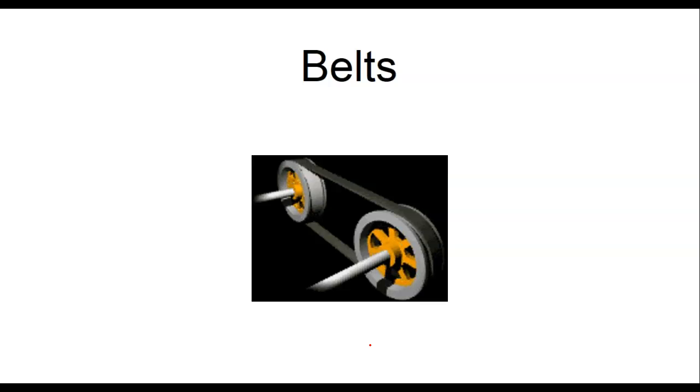So if you start something up real fast, a chain might have problems and a chain might actually break, but the belt actually just gives a little bit. With belts, you can have a lot of slop. The alignments are not as critical between your driver and your driven, and we don't call these wheels, we call them pulleys. So we call them pulley wheels.